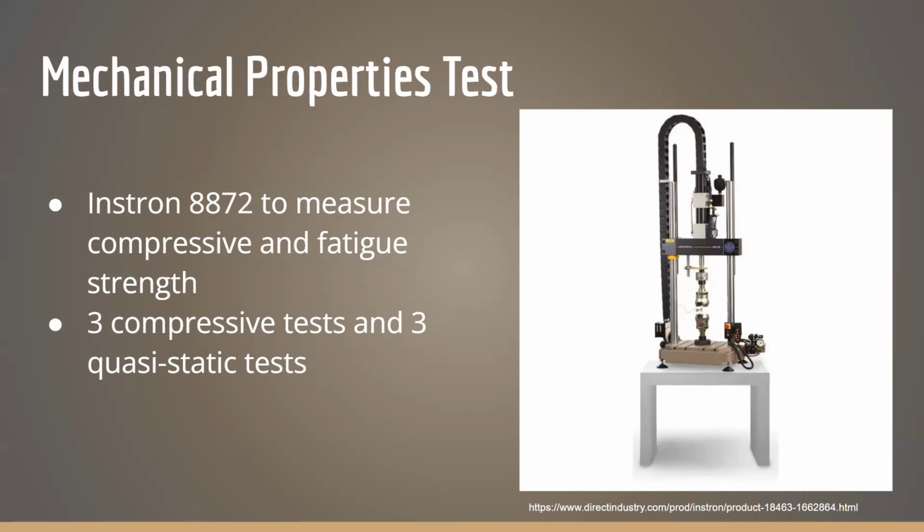This will also allow us to observe the scaffold's failure to ensure it is not catastrophic in vivo. The quasi-static test will also run at 1 millimeter a minute and will cyclically load the specimen around 100 newtons to test fatigue.